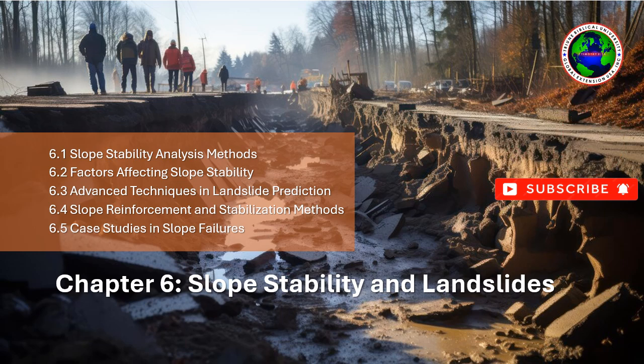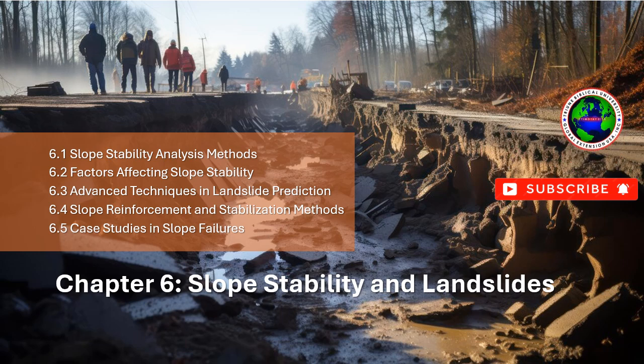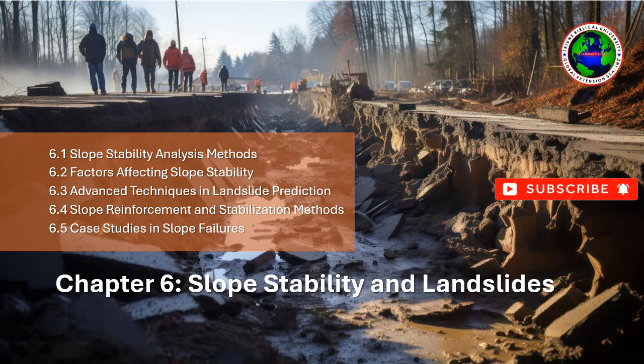Seismic refraction and reflection. Seismic surveys are used to assess subsurface conditions by measuring the travel time of seismic waves through the ground. The variations in wave velocity can help identify soil layering, bedrock depth, and areas of weakness, such as faults or fractures, that may predispose slopes to failure.